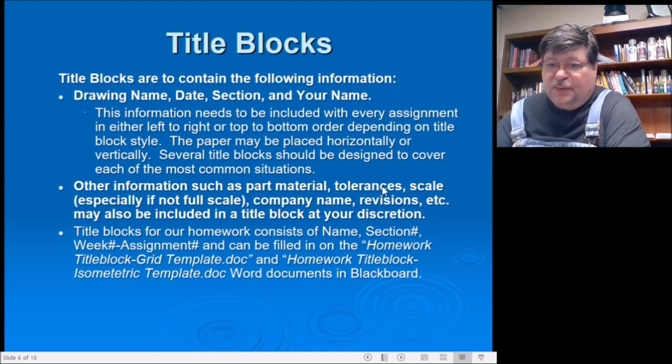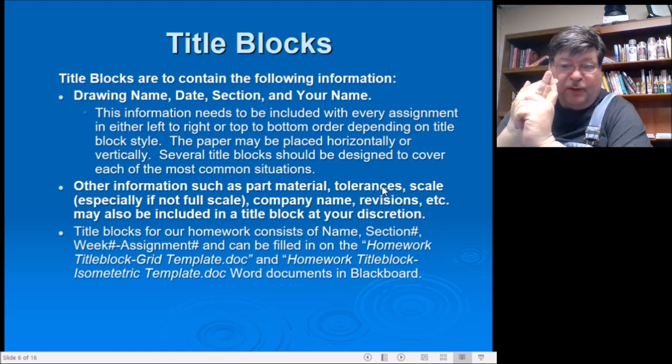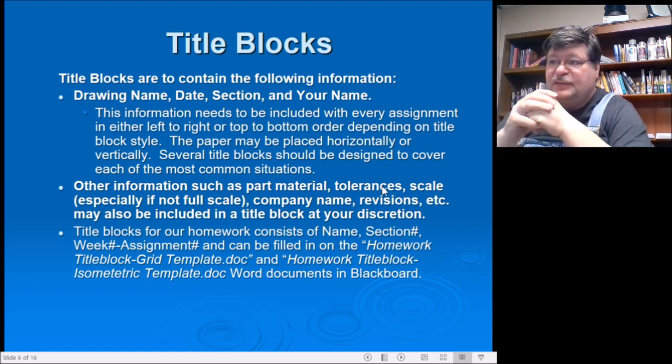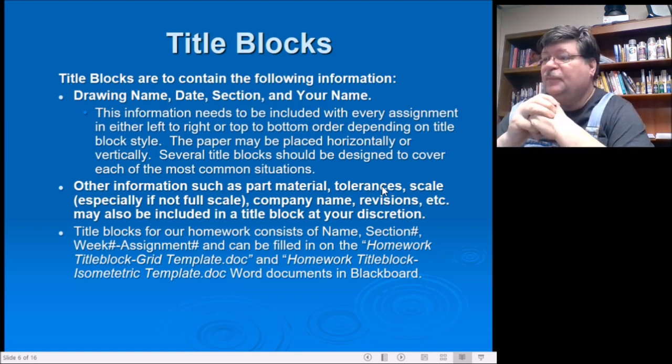So title blocks, for a company that has construction drawings, tell you everything you need to know about that drawing that isn't in the drawing, or dimensions or notes about the drawing. Title blocks show the owner of the drawing, whether it's GM or Ford or some architectural engineering firm. But you'll have things like the name of the drawing. Sometimes it's a sheet number, like M1 for mechanical and P1 for plumbing or something like that. You'll have the date on it, or maybe several dates. Every revision would be dated.